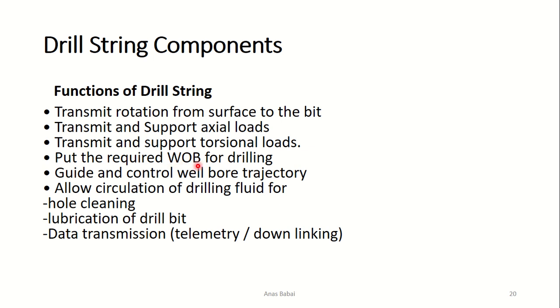If it's more, it will cause damage to the drill string, bending and breaking. If it's less, it will reduce the drilling efficiency of the drill bit. And the drill string allows circulation of the drilling fluid.